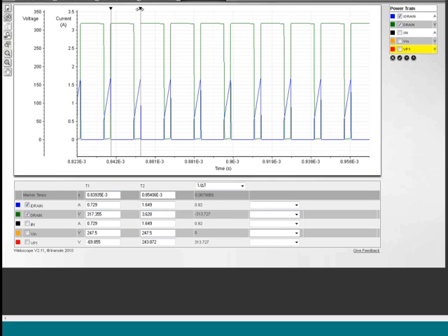If I were to expand this out, again, that's going to give me my delta time between those 2 points. It's very convenient for measuring frequencies when you have a switching waveform. There are measurement functions built into this tool, so there's a whole host of measurements that I can get. If I click RMS, it's going to give me the RMS of all the data for I drain. So here I can see I've got 530 milliamps for I drain.